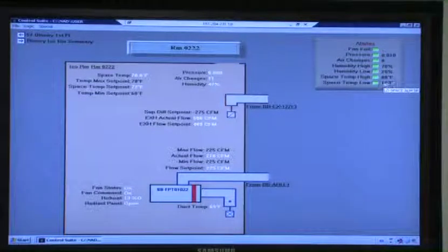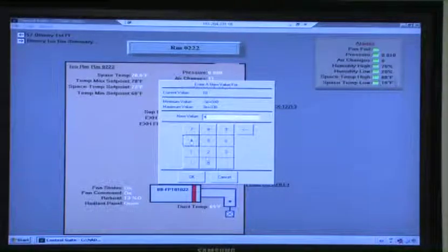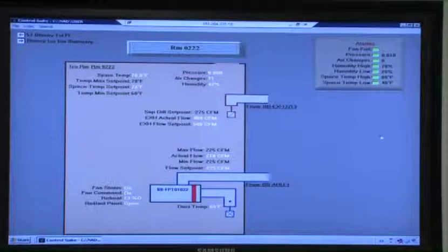So, like I said before, those are adjustable. Once we figure out the things, we can go in there and make all the adjustments necessary. They gave us control of it. We can go in and double click it and make it just 40, trying to avoid a bunch of nuisance alarms. Guys will walk in and shut the hand valves off and the room will drop to 65, 60 degrees, and you'd have a million nuisance alarms to get the whole building straight. Exactly. Once we get close to turnover, we can adjust our alarming properly.